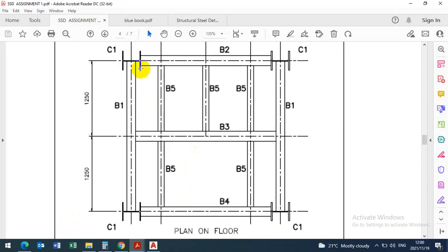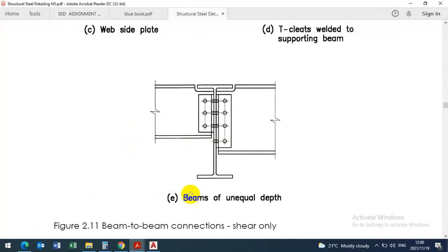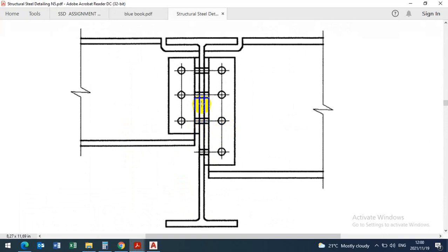Then when we come to beam 1, it is going into the web of the column. So at this point, don't notch beam 1; we will just do notching of beam 3 when we come to answer beam 3. On beam 1, I only expect you to show me the hole positions in the web here, where this beam 3 will be connected to, which means that we are going to do something like that. For beam 1, looking from the top view, it's going to be hidden details. Why will everything be hidden details? Because of the flange. This flange for beam 1 is hiding everything.